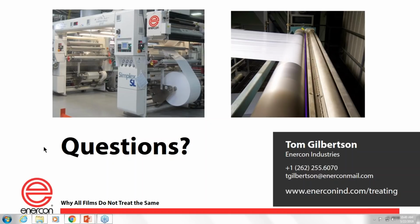So Tom, we've got a couple of questions related to the thickness of materials and how that might affect treatment or watt density, if at all. And also a specific question on a 12 micron PET that seems to be problematic for someone with a printing application. Well, typically, for most film converting applications, and notice I put a qualifier in there, film converting, I'm not talking about sheet, I'm talking about film. So films meaning anything from 0.5 mil to, let's just say, 20 mils. Let's pick a wide range. In that range of common films and converting applications, the film thickness doesn't really play a role at all.